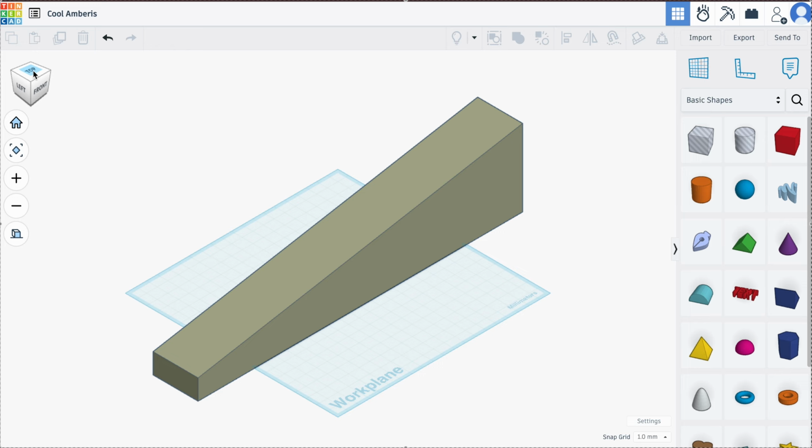Now, with this particular activity today, where you're going to create the view or the model of your CO2 car, it's going to be just a few basic steps. So you should have your drawing of your final design with you. We're going to come up to the right hand side here where we've got this workplane tool. You are going to click on that or drag that to this side view here. We're just going to place it in the middle, and that is going to allow us to now draw on this plane over here.